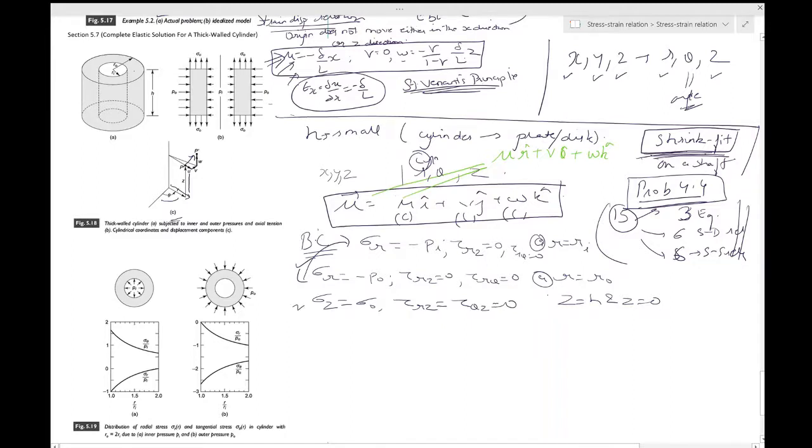Okay, so you want to find this value. Because there's a radial symmetry, you don't have to worry about it a lot. So let's start with the theta component of the displacement, and we shall look for a solution in which this becomes equal to 0, and in which all stresses, strains and displacements are independent of theta. This is happening because of the radial symmetry.